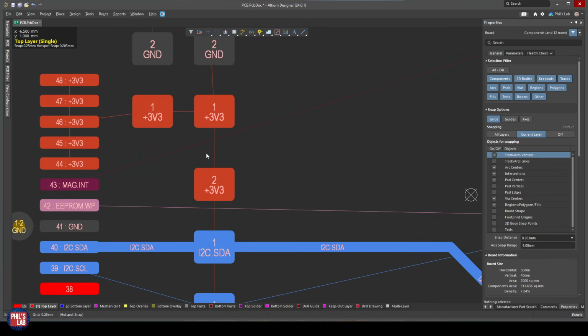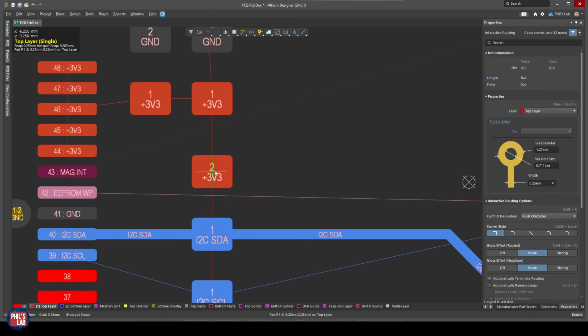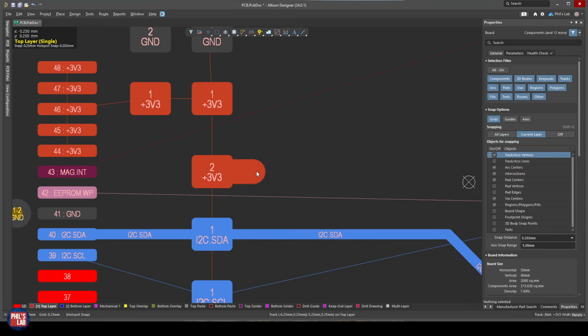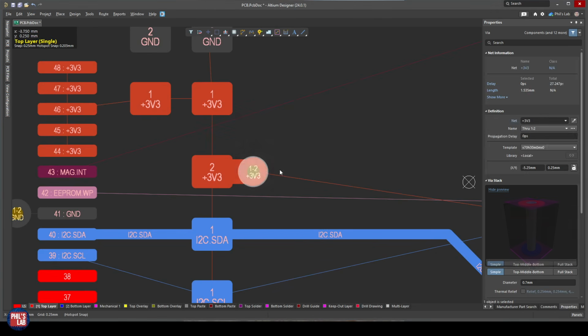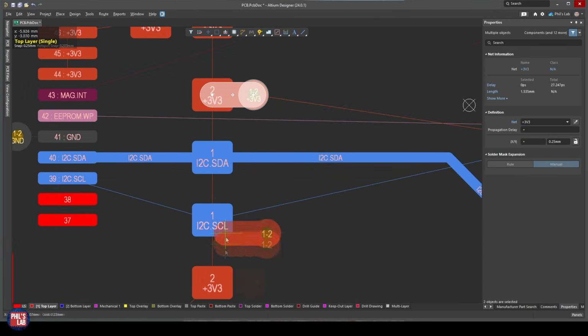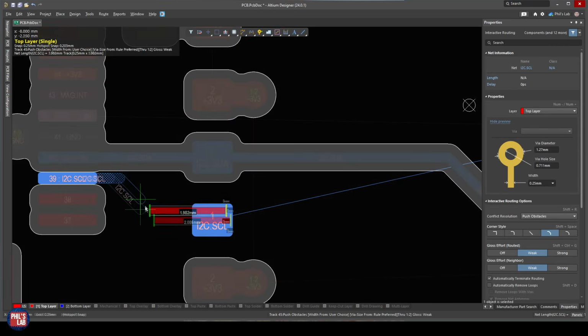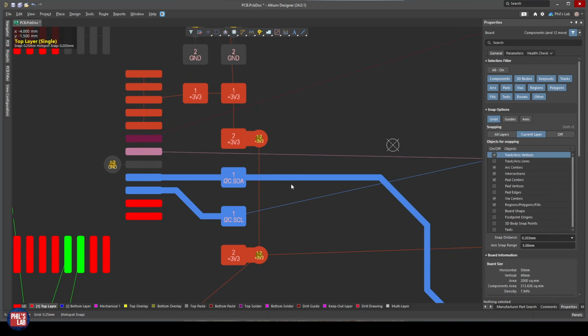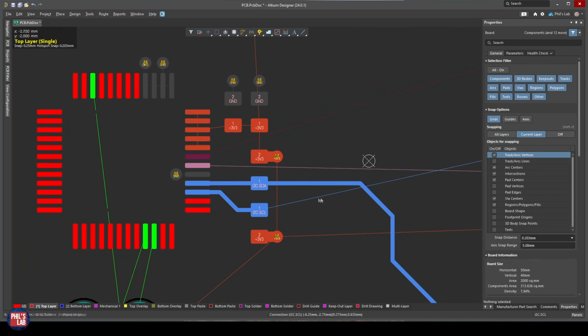On the other side of the pull-up resistor, if you have an internal power plane or you're using polygon pours, all I would do is route out a wide trace, so a power trace, short and wide, and place a via close to the pad. For example, like so, I can copy that structure and place it, for example, at the SCL pull-up, so signal traces versus these power traces from the pull-up. So a very, very crude and simple example. Again, you can either route as a branch or through the components if you have multiple of these ICs. Just keep them short if you can.